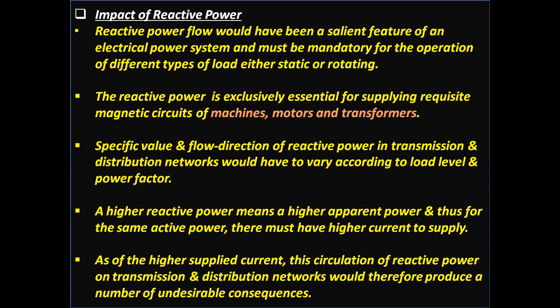The reactive power is exclusively essential for supplying the requisite magnetic circuits of machines, motors, and transformers. The specific value and flow direction of reactive power in transmission and distribution networks vary according to load level and power factor.